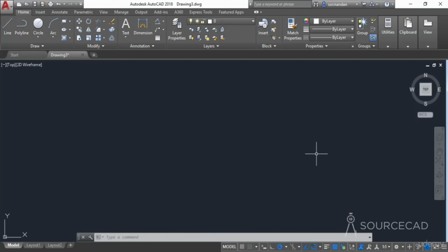In this video I will tell you about polylines and splines. Let's start with the polyline tool. Here on the draw panel you'll see this polyline tool, and when you select it, you'll find its behavior is very similar to that of the line tool. Let's make some geometry with this.